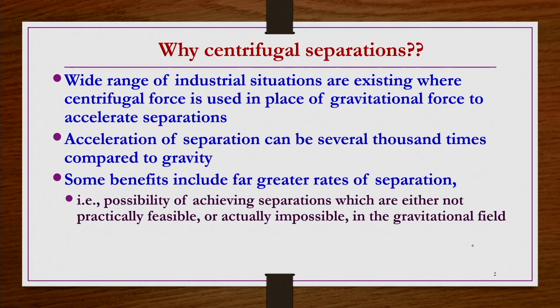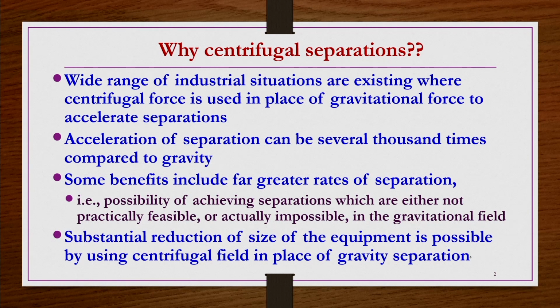Let us say you have very fine micron-size or sub-micron-size particles suspended in air, and you want to purify that air. If you try gravity separation, that is going to take a very long time, or sometimes it is not even possible. But if you apply a centrifugal field for such cases, the acceleration of separation takes place, and the separation of those particles can be easily done, as is sometimes done in cyclone separators. Substantial reduction of equipment size is also possible by using a centrifugal field in place of gravity separation, as I already mentioned.